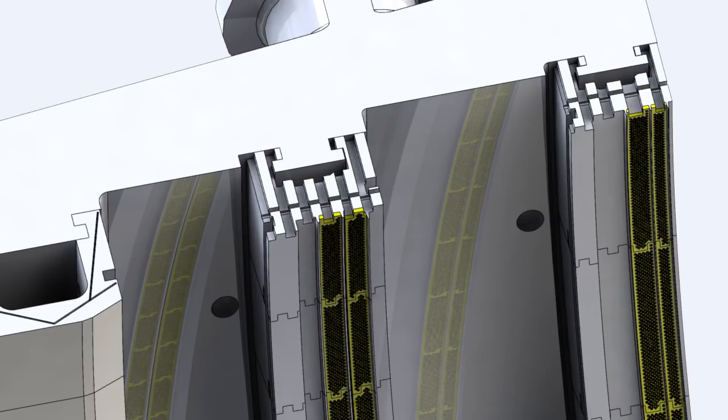The second and third stage shrouds have teeth that mate with teeth on the tip of the second and third stage buckets. This labyrinth seal minimizes tip leakage. For better tip clearance, a honeycomb seal is integrated on the second and third stage shrouds. This honeycomb is relatively soft material. The cutter teeth on the tip of the second and the third stage buckets open a slot on the honeycomb seal without any material transferred, providing tighter clearances to improve the unit efficiency.